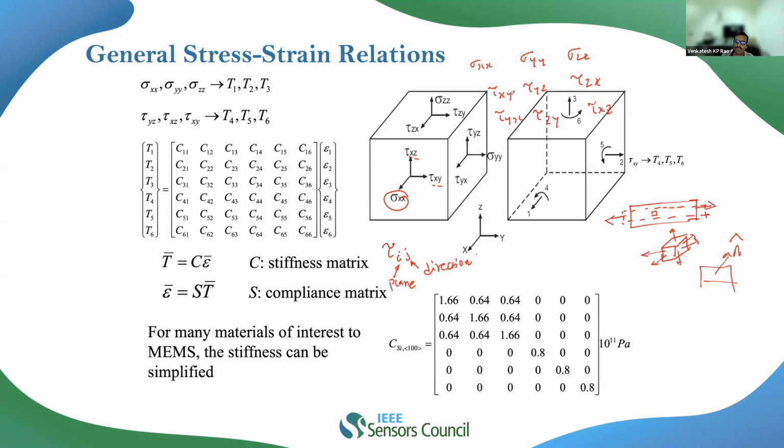Now, you can see the similarity between these two, that x and y have just interchanged positions. So that's why we say tau xy is equal to tau yx, which is called the cross shear, right? And we can even derive that cross shears are always equal.